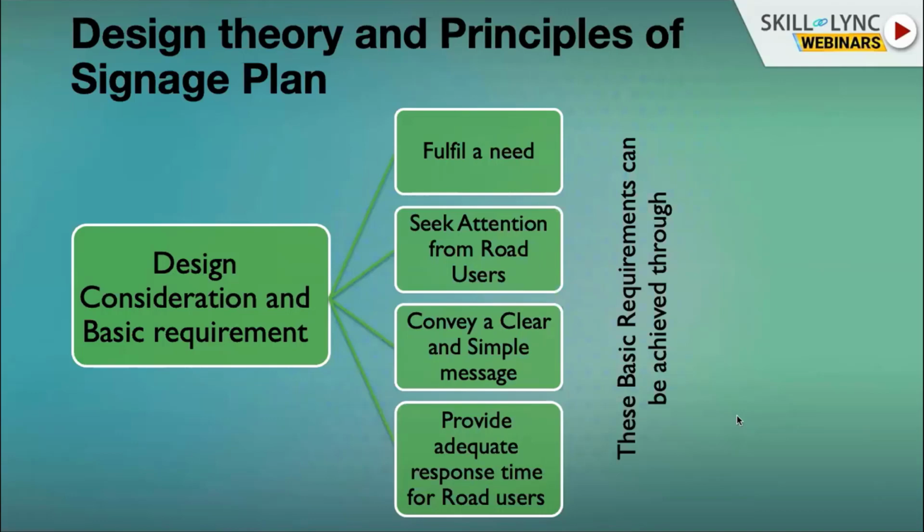Text used in the directional and information signs should have information in both the official accredited national language and maybe a state language as well. It should always be placed at an appropriate location where it provides adequate response time to the road users.